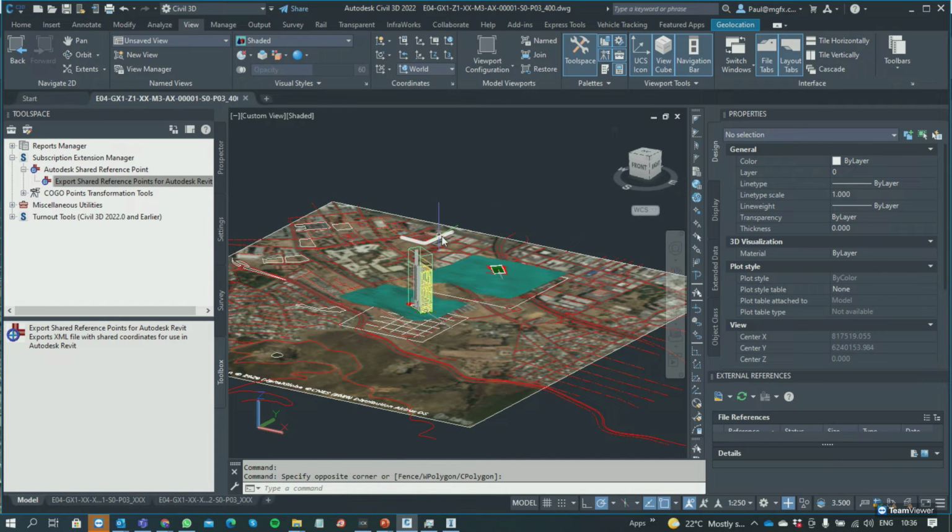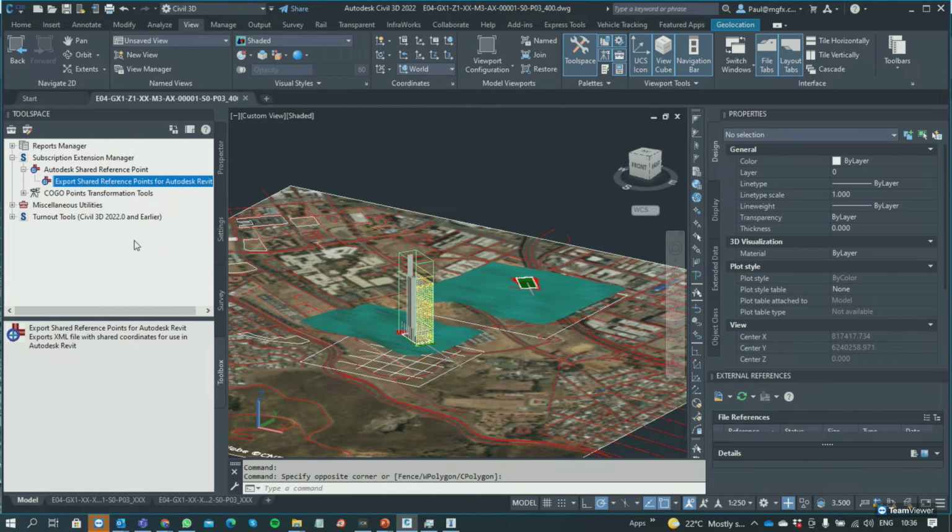And in Revit, you can then reverse the process and set your coordinate system correctly in Revit. After that, you'll find that your surfaces can be exported once you've got the same coordinate system within Revit and within Civil 3D. That would be a shared coordinate system within Revit, that would be what the BIM manager would set up.